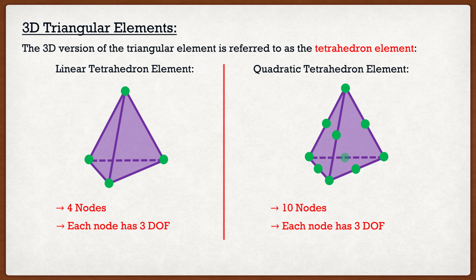When we're dealing with the finite element analysis method, we typically have hundreds, if not thousands of elements. So if we have 1,000 elements and each one is 30 by 30, I don't want to be taking that double integral. Therefore, we are going to start introducing ways that we can calculate the stiffnesses of these matrices without the need of actual integration.